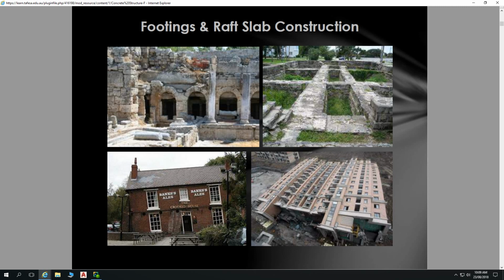So this is a piece of Hebel, a piece of aerated concrete, it's incredibly light, I'll pass that around. Notice that it's got steel incorporated in it for tensile strength. And you see the big chunk taken out of that. We get a big chunk taken out of that because aerated concrete, or concrete in general, is not very good in tensile strength. That's why we can break sections off of it.